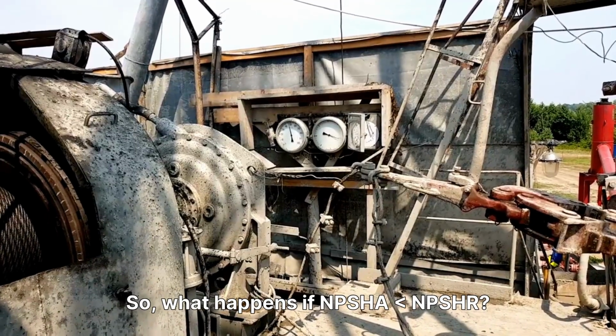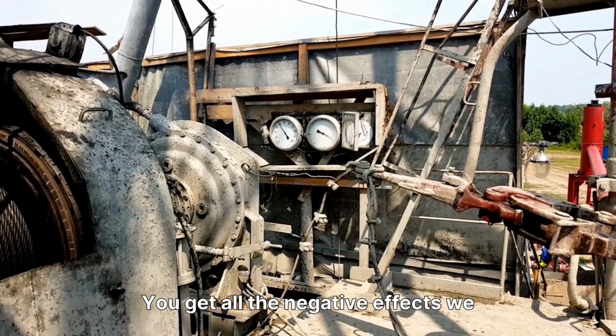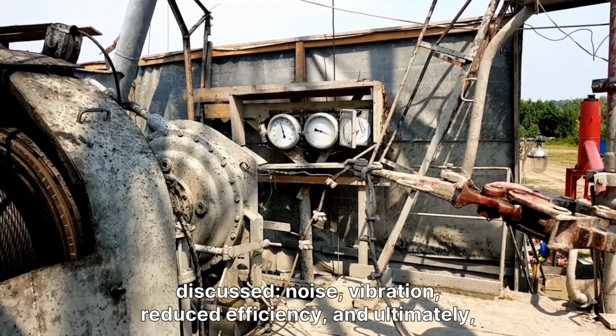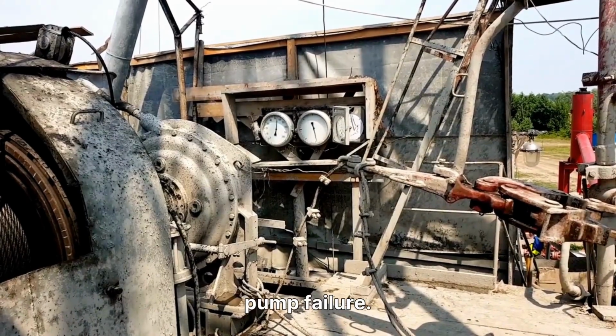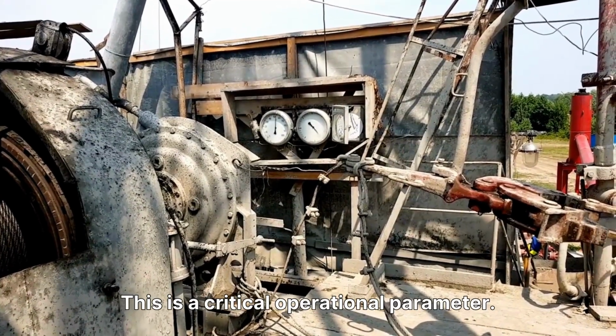So what happens if NPSHA is less than NPSHR? You get all the negative effects we discussed: noise, vibration, reduced efficiency, and ultimately, pump failure. This is a critical operational parameter.